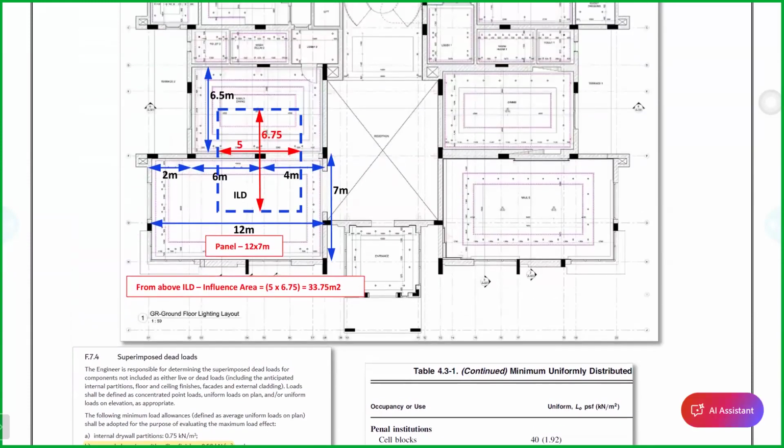See, for the beams, you can see the loading: half of the span, half of the loading is going to be transferred to the beam, right? Slab, you could see one-way slab or two-way slab. If the ratio is greater than two, it is a one-way slab. If it is less than or equal to two, it is a two-way slab. You get it? What is a one-way slab? The load is going to be distributed to half of the beam. Okay, this is only the longest side of the beam.